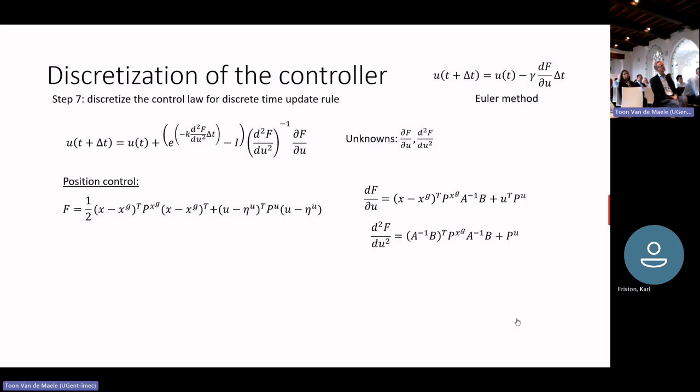Don't jump into this, because the moment your time steps are small, none of those controllers will work. None of them. If you do this, because if your differential equation is by default stiff, then you are already running into problems very quick. So either use this, it used to work with all the free energy stuff, or also go for trapezoids or Runge-Kutta. But make sure it's not one gradient dependent.